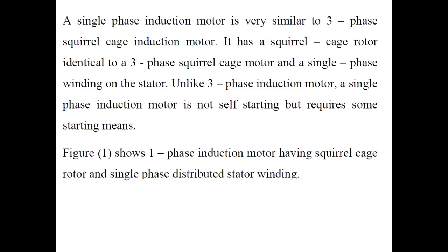Now single-phase induction motors are actually very similar to three-phase induction motors. It has a squirrel cage rotor, identical to that of the three-phase, but it has a single-phase winding in the stator, unlike the three-phase induction machine. Consequently, because it has a single-phase stator instead of a three-phase, the single-phase induction motor is not self-starting and requires some mechanism to help it start.